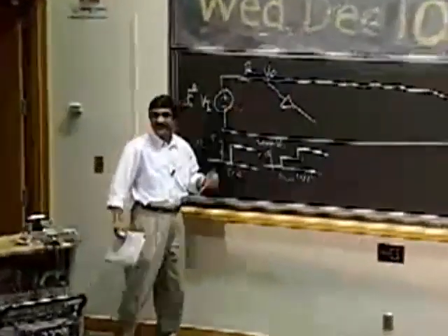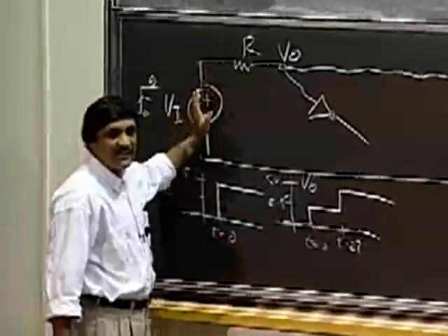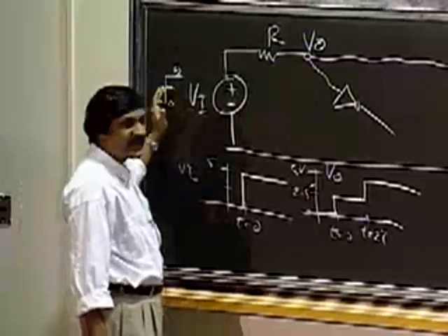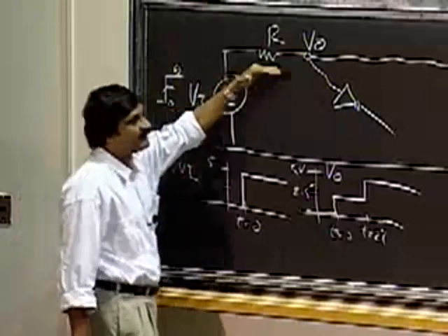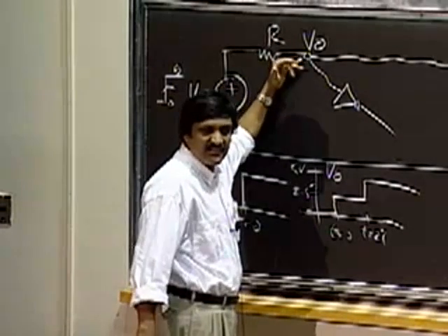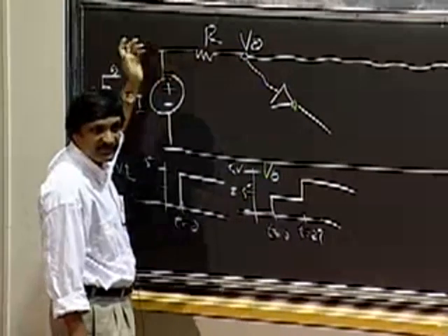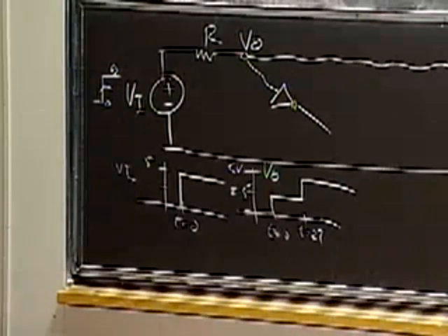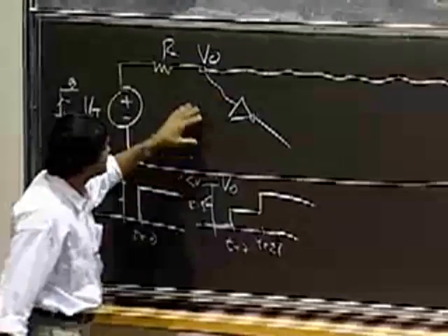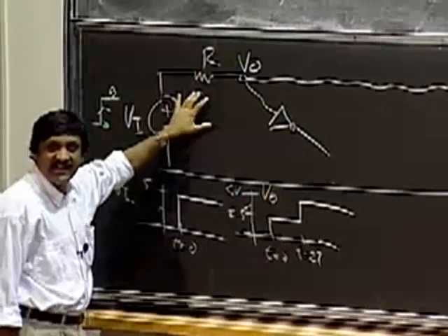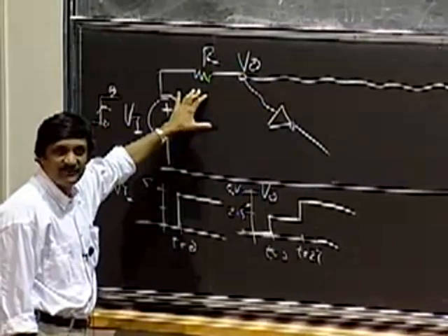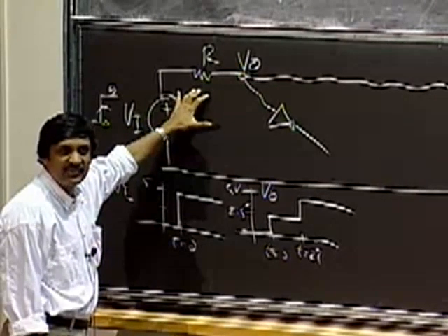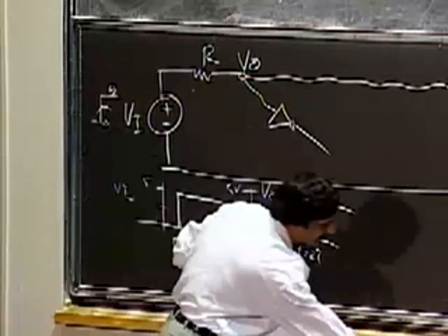So the theory is that the step here is actually, think of it as an electromagnetic pulse that goes from 0 to 5. And things in real life don't travel instantaneously. So there's something about a wave that flies down. And the wave goes to the end, flips, and then comes back, and then establishes the full voltage here. So that is indeed at the root of what's going on. And let me put it in layman's terms and describe the details of what's going on here.